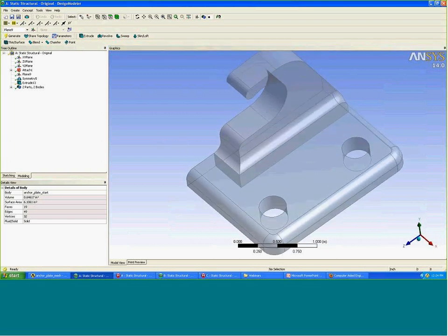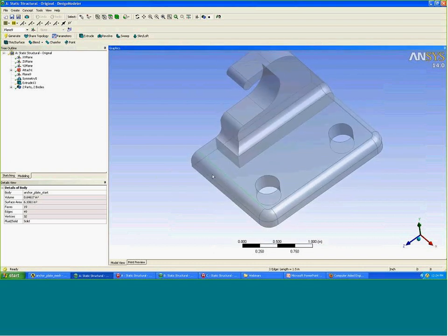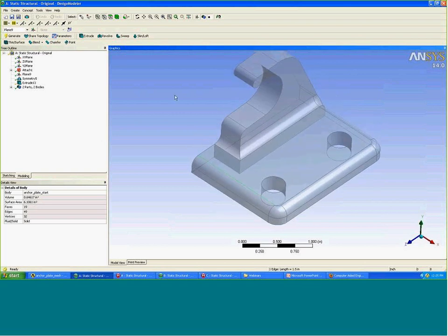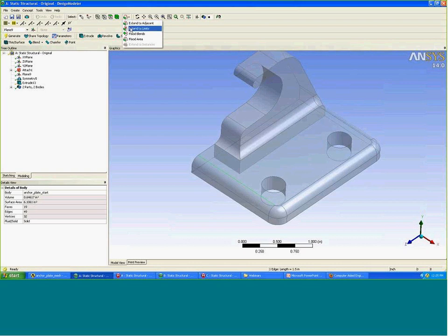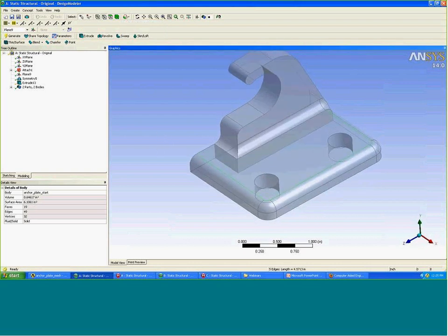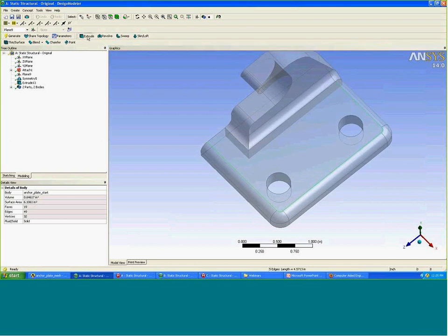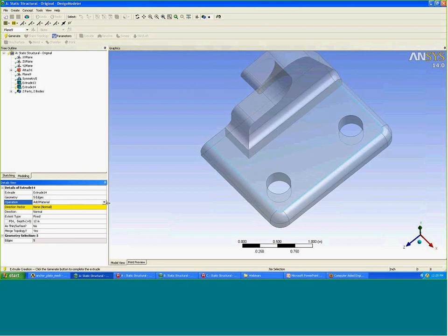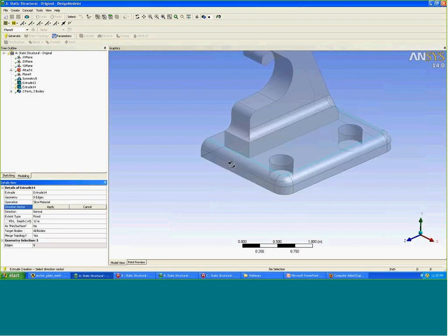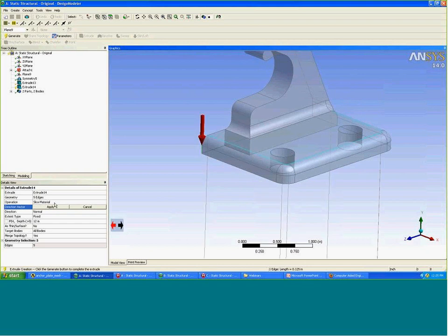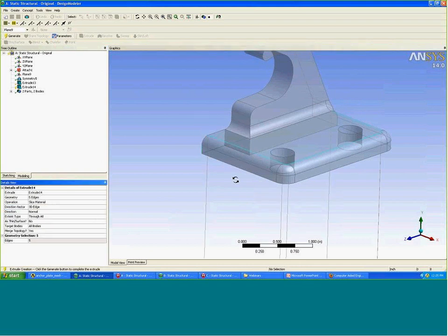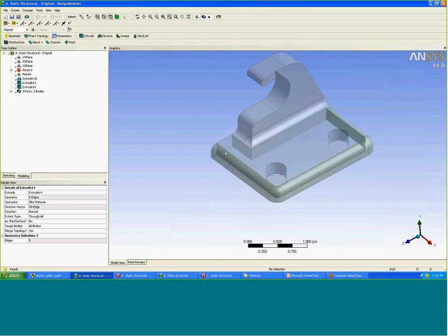What I want to do is slice against the base plate and cut off this rounded edge region. To select one of these edges, an easy trick here is that I can extend my selection, in this case to the limits. That'll select for me all 5 edges along this fillet on the edge here, which I can use as the base object for another extrusion. So it's over to a slice. Again, I slice down through the base plate, and it goes all the way through. All right. Now you have 3 bodies in my model.